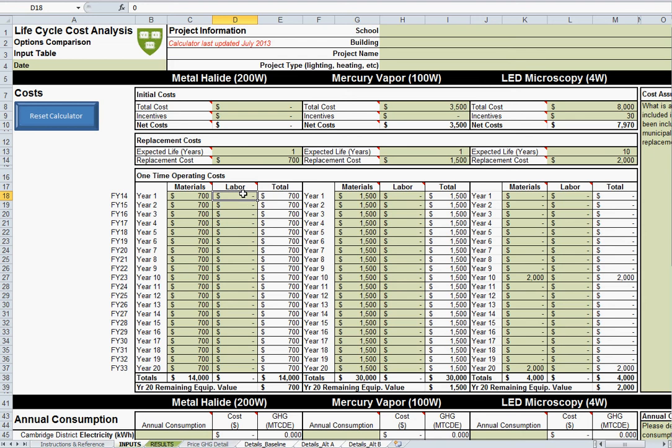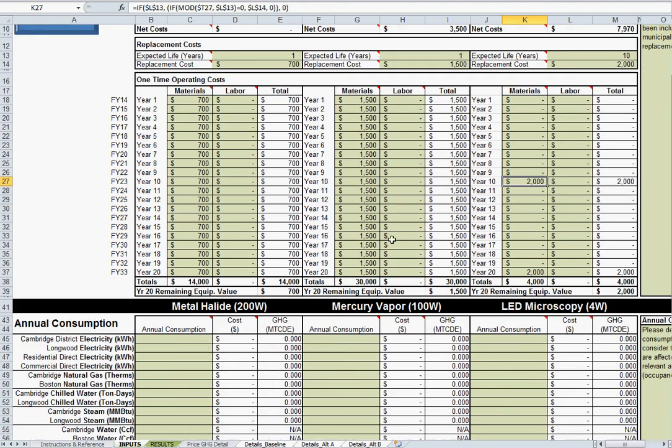If we're looking at large-scale fluorescent lighting, lamp replacement can be very big. You could have a facility with thousands of lamps in it, and even at 5 minutes per lamp, that adds up to hours and hours of labor that you have to do every time. It's actually one of the big drivers of LED savings, frequently the lamp replacement schedule. This is not uncommon. The scale of the numbers is a little strange, but the general concept of LEDs far outlasting their counterparts is very common, both at the process, microscope level and at your typical lighting scale as well.